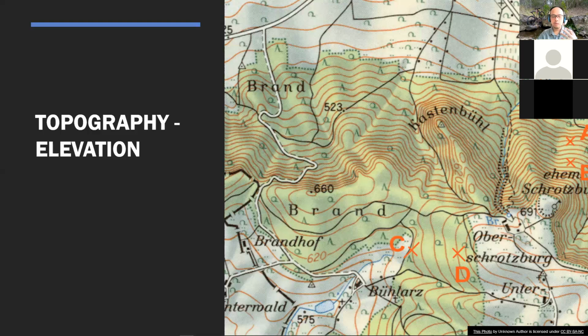And to limit the map's visual complexity, you can divide the 150 meters into 6 classes. I mentioned anywhere between 5 to 9 classes. So 150 divided by 6 classes, you get a result of 25 meters. So the way you would graphically represent the changes in elevation is in 25-meter increments.